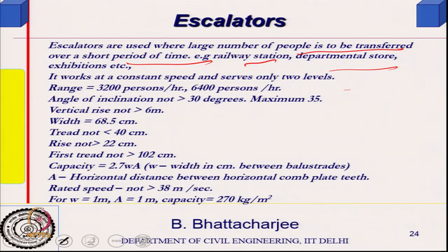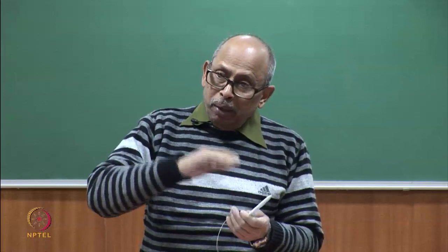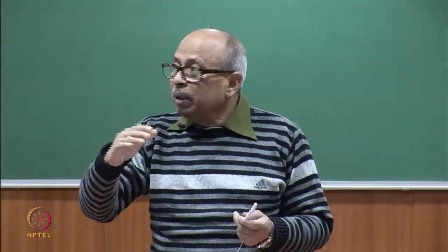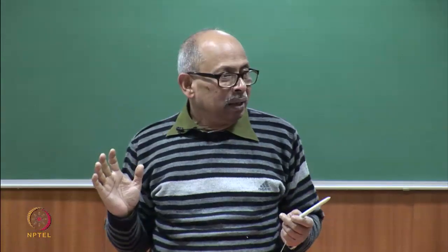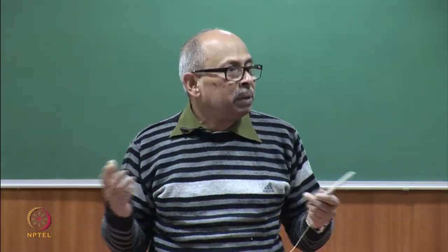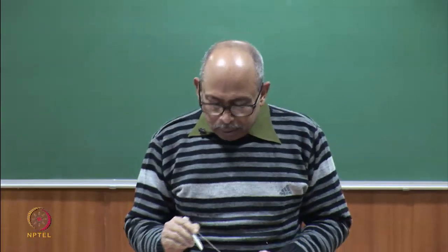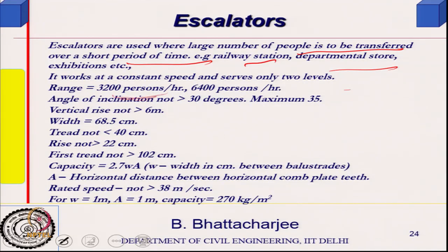But where people have to go from one level to another only, and you want them to see the surroundings, like in a departmental store or showroom, then escalators are good, right. It will handle something like 3,200 to 6,400 persons per hour. So it handles a very large number of people.